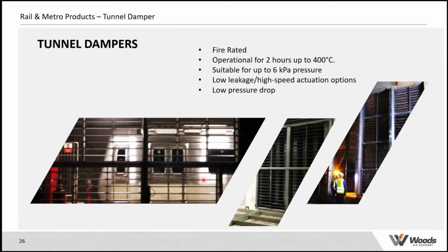And the last element here would be the fire rated dampers. So again, the fans are normally mounted in pairs, so there's a run and a standby one. If one of the fans was to go down, you wouldn't want the air to be recirculating around the fan, so you need the ability to isolate it, so the system still works, and also gives the ability to work on or maintain the equipment because it's isolated from the system. Again, they need to be rated or certified for the same temperature as the fans, so you have a complete system which is all certified for the application.